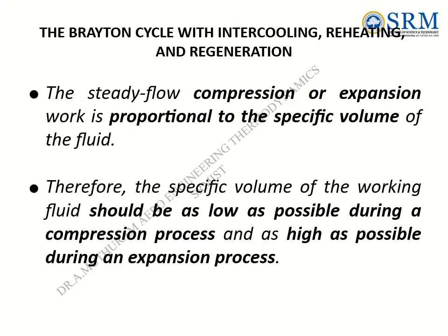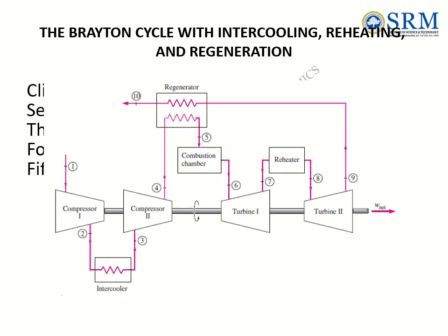The steady flow compression or expansion work is proportional to the specific volume of the fluid. Therefore, the specific volume of the working fluid should be as low as possible during a compression process and as high as possible during an expansion process. The Brayton cycle with intercooling, reheating, and regeneration.